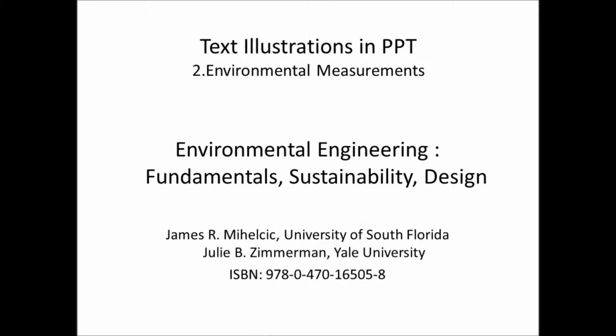2.2.1, Using the ideal gas law to convert parts per million to micrograms per cubic meter. The ideal gas law can be used to convert gaseous concentrations between mass to volume and volume to volume units. The ideal gas law states that pressure times volume occupied equals the number of moles times the gas constant times the absolute temperature in degrees Kelvin or Rankine. This is written in the familiar form of PV equals nRT, or equation 2.6.